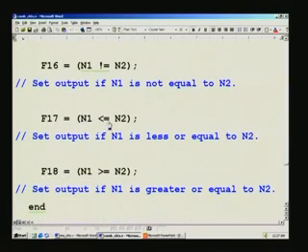In an always block you use that one. You should distinguish the difference between them. Here it has a different meaning; it means precisely less or equal to. In an always block, in a non-blocking statement as it is called, that is mere assignment.